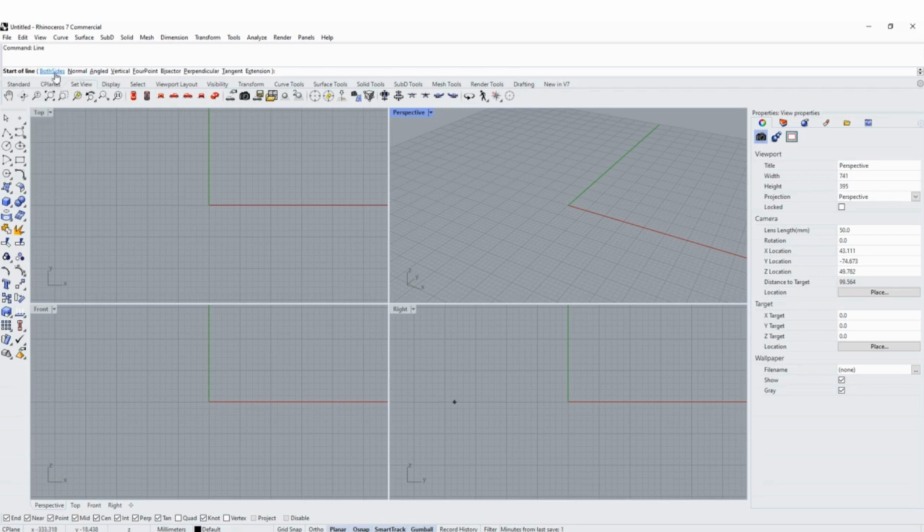Hit enter or the space bar, and then you can already start drawing a line. So you can put the command that you're interested in here, and then hit enter, and it works. All the items above that are just the history of what commands you have used in the past. We only had one command, which was line, but still you see the history over here.